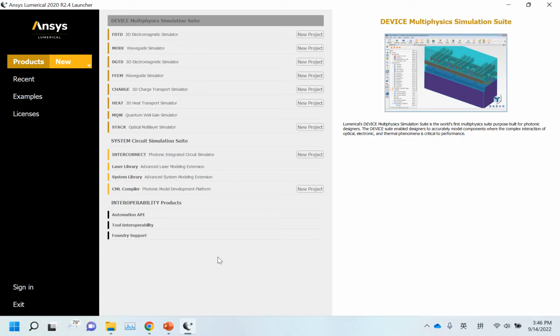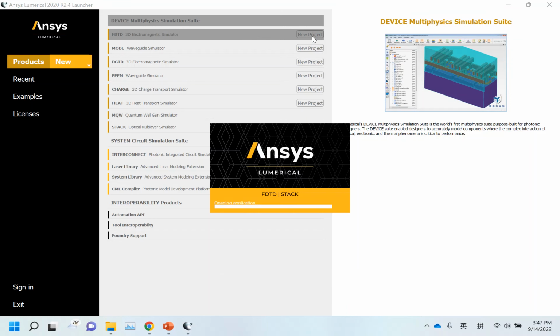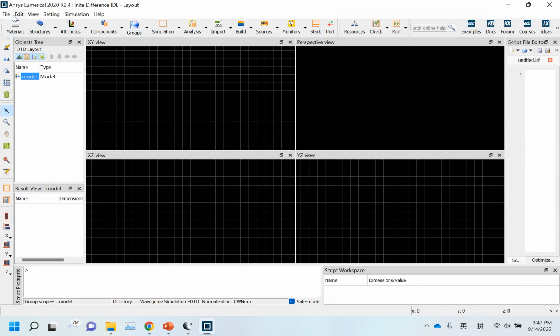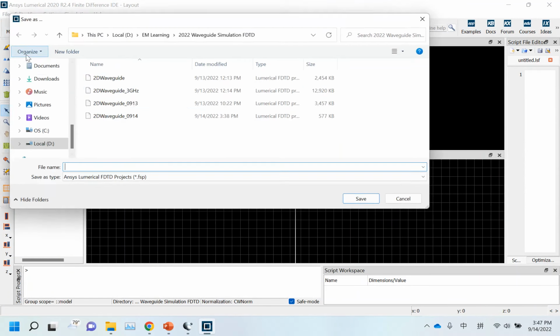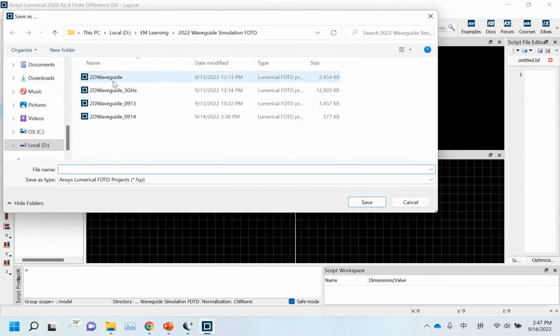Hey guys, I made this numerical FDTD tutorial video so that it can be helpful when you do the project at home. As we discussed in the class, first we create a new project of FDTD and we save it. Click File, click Save, and for example, we create a name as 2D Waveguide Test.